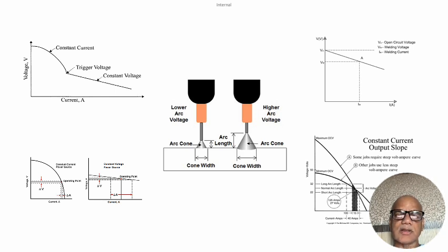in the drooping characteristics and in the flat characteristics, the variation can be up to 15 amps or to 100 amps, and that is something which helps in maintaining either the constant wire arc length, or in the electrode case, where we are going to move the torch holder or the electrode holder downwards as well as forward in the direction of the welding. So let's move to the current characteristics.